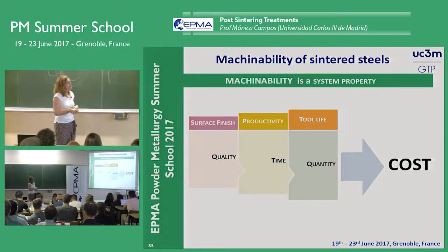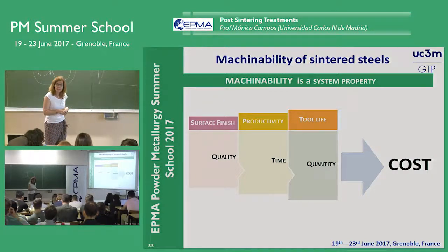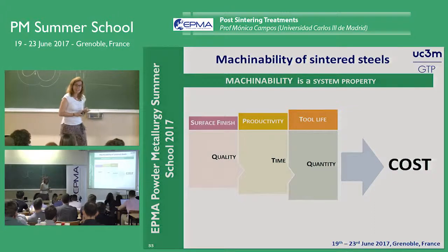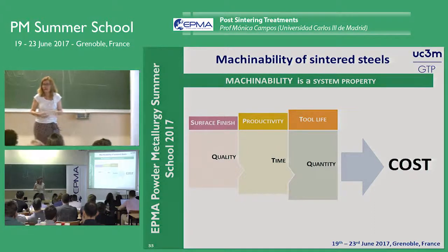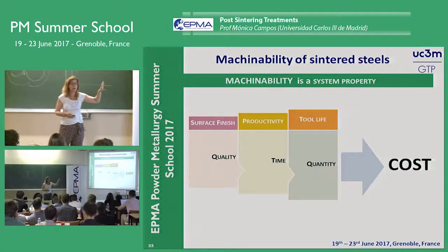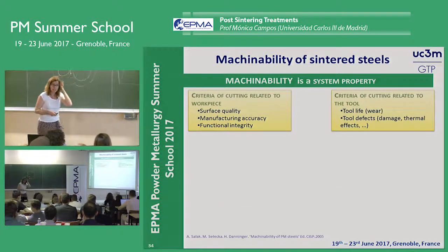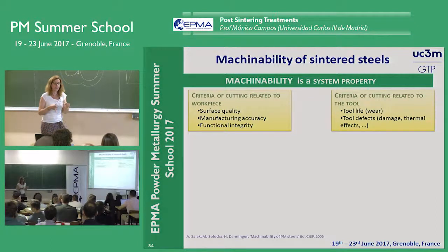We need to take into account the surface finish, that means the quality of the final component, the productivity, that means how much time I have to invest for machining the component, and the tool life. How many cutting tools I need for machining the component. And all of them are going to give us the idea of the cost of our step in that case.